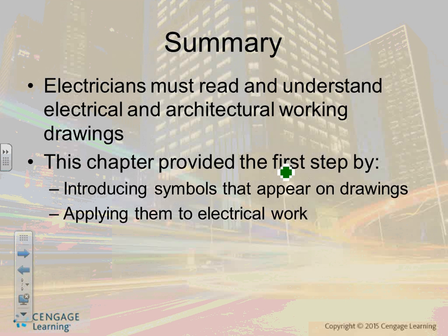Keep moving, guys. I'm going to go to page 42. These are your disconnects. If you have an XXA disconnect, this is a disconnect switch, unfused type, size as indicated on the drawing. XX indicates the amp rating. So when you say 100 amp, right next to the disconnect, that's the disconnect size. If you put an F in it, it has 2 sizes there: one for the disconnect and one for the fuse.